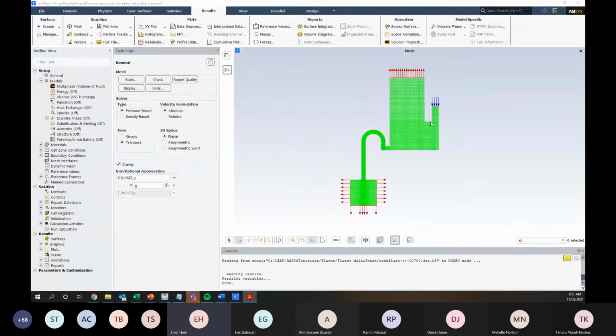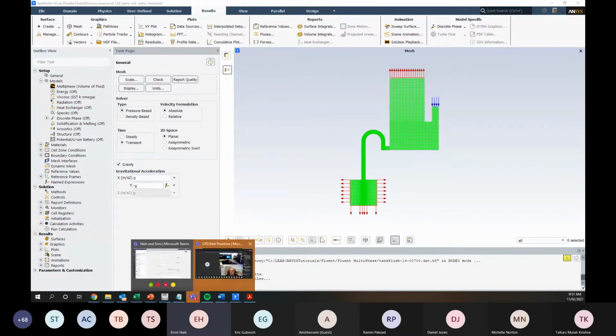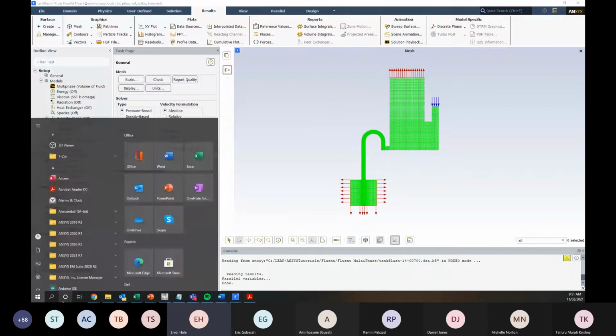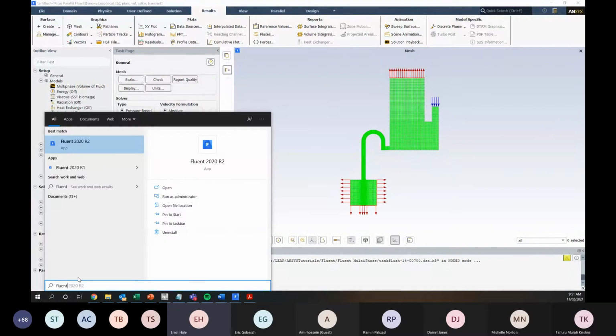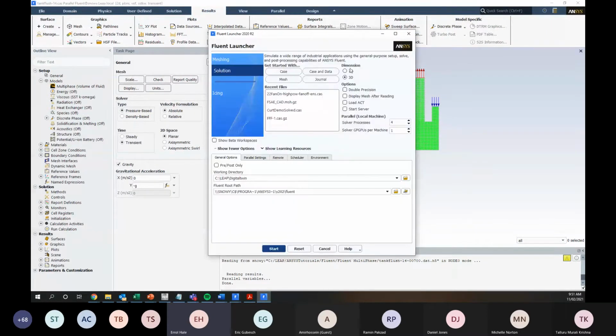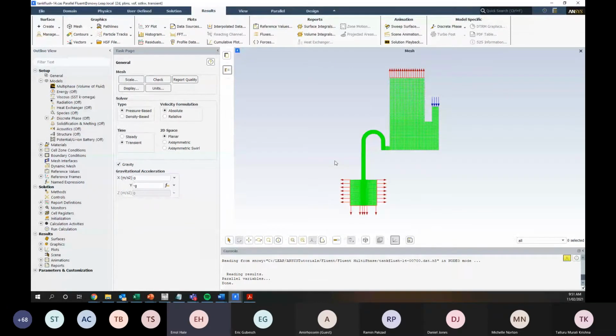So you can see we've got a mesh. This is 2D instead of 3D. So when we're doing our Fluent, just remember to click 2D up here instead of 3D. It used to be that if you didn't select the right dimension, the error message would not be necessarily that helpful in telling you that you're in the wrong dimensions. But luckily now it does tell you if you're in 3D and you try to import a 2D case, it says wrong dimensions. It never used to do that. So people would always get confused as to why it wouldn't import their case file.